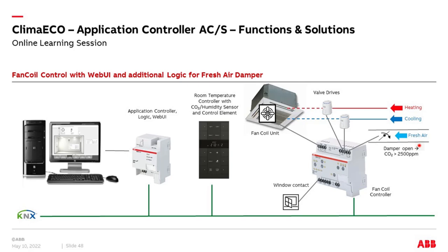And what did I do here? I said, oh no, in my air pipe into the room, I have the option to also control a damper, and this damper is related to fresh air coming from outside, for example. And I would like to control this the following way: depending on the air quality, I would like to open and close this air damper.